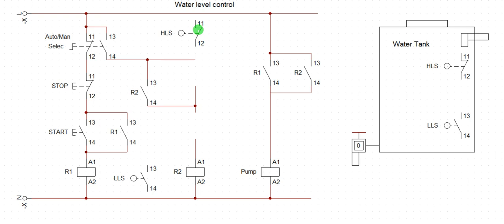A wiring diagram does the wiring connection from point to point. But schematic will represent the symbols in a logical manner. All right. That is why I said I'm not taking you to automation yet until you understand the operation sequence of a particular process. After this, I will take you to automation software. You're going to convert this to a ladder diagram and use the ladder diagram to write the program and download to PLC and simulate with PLC.